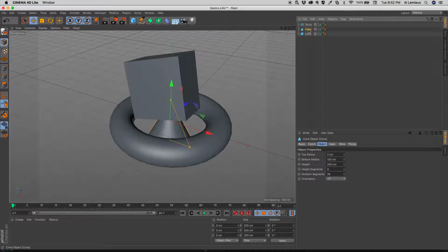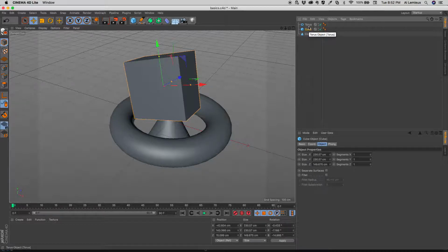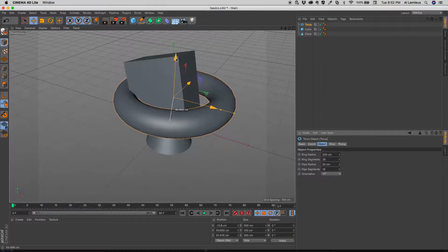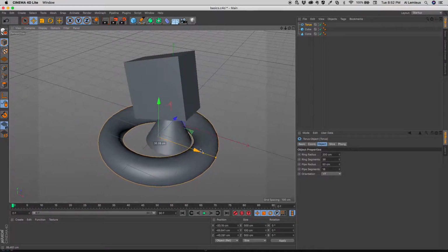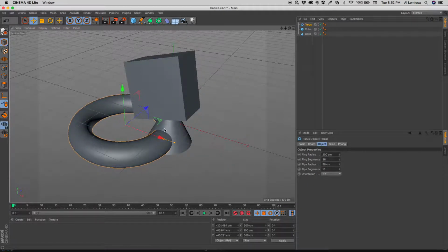If I want to move the position of these objects, I can drag down or drag up to change the position of these objects. But to manipulate each object, you need to select the object first, and then you have the controls, and then you can move it around. And you can already kind of see some of the potentials for modeling here. Just by interacting with other 3D elements, you can create things like rings and other things like that.